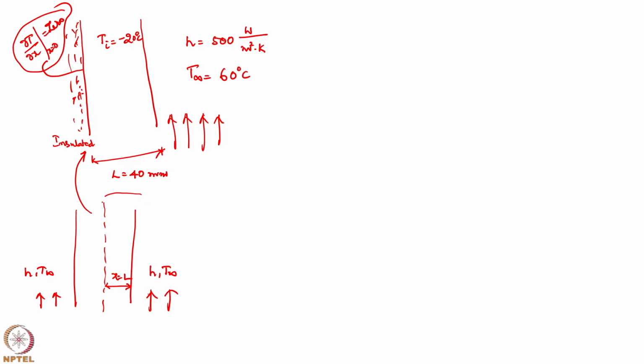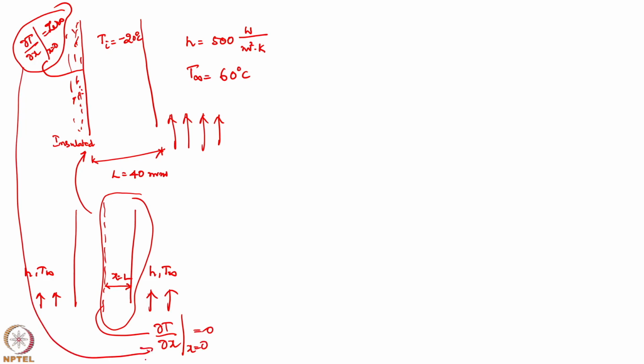So it is insulated, that is why. In the solution we had, we also took dT/dx at x equal to 0 as 0 by symmetry. So both are the same, and that is why I can apply this solution to this case.